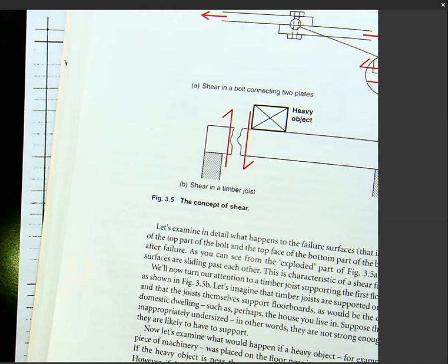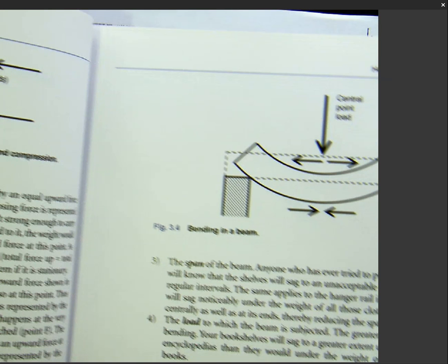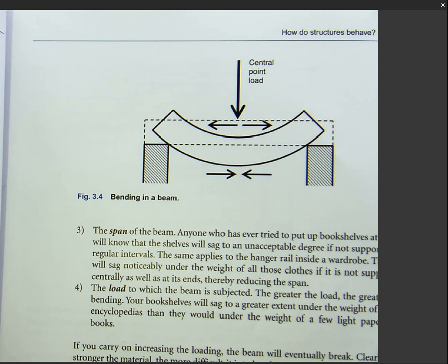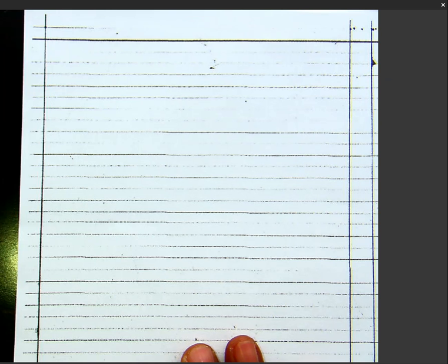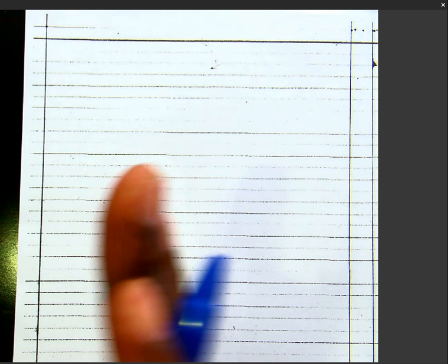Then we talk shear force, and you draw a shear force diagram that is going to give you a picture throughout your beam of how the forces are in the beam. And then they will bend the beam. They will try to bend the beam. Then you talk about the bending moment diagram. Again, you draw a diagram throughout the beam that is going to give you an idea of how the moments are distributed over the beam. I hope we understand now what we need to do with our forces.